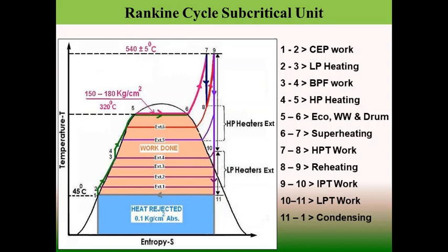There may be natural or thermal circulation, that is created by thermosyphonic action between the water coming down the downcomer tubes and again moving up to the water walls. There is a density difference, and this density difference gives the force for circulation. Or there may be a pump placed at the downcomer bottom location, which will give forced circulation or pump circulation.